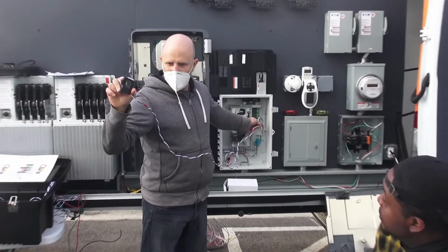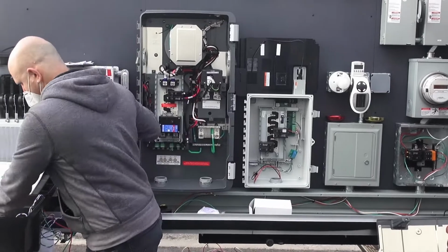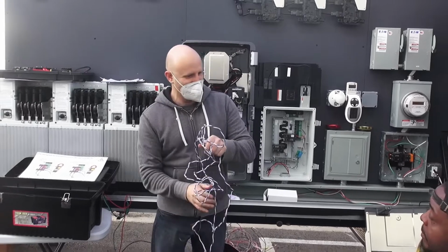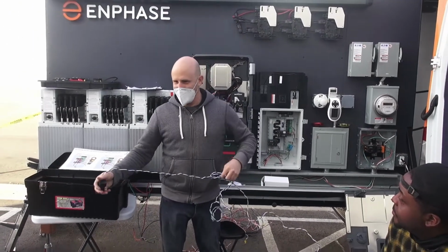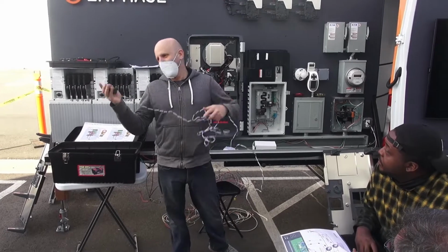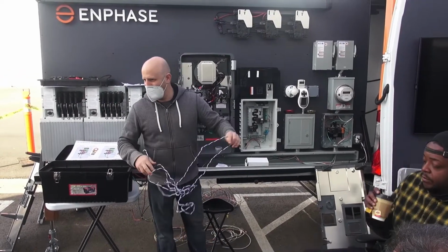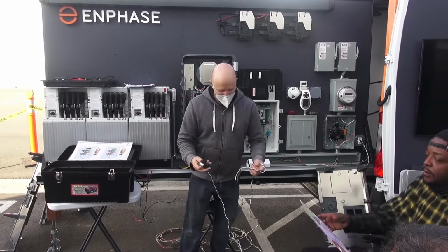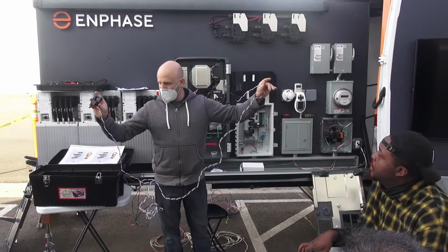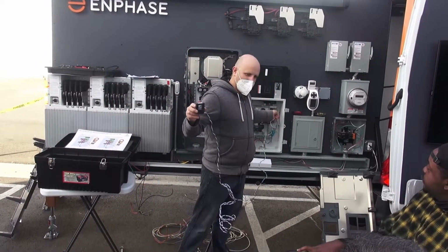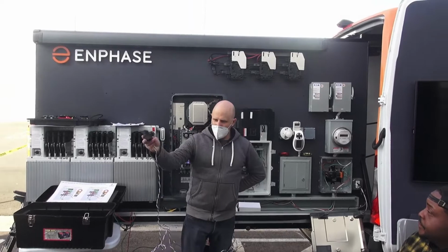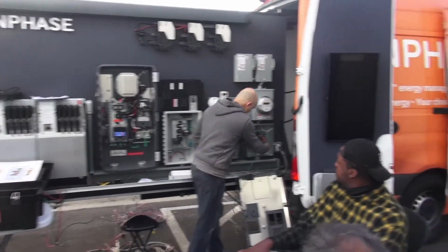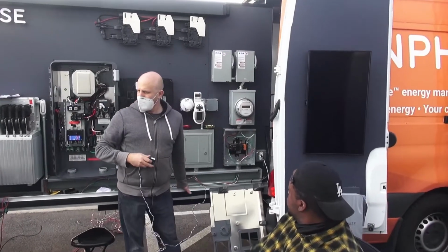This is CT number 1. Oh, I grabbed the wrong color, the black one. Technically red or black, it doesn't matter, but I'm going to go with electrical industry tradition. If you go to Austin, Texas, who knows? California, I don't care about the colors. It's the principle that's more important. Okay, so I'm going to call this one CT1 because I wired it on the CT1 terminals. My ask to you is you tell me which conductor over here is the L1 conductor.